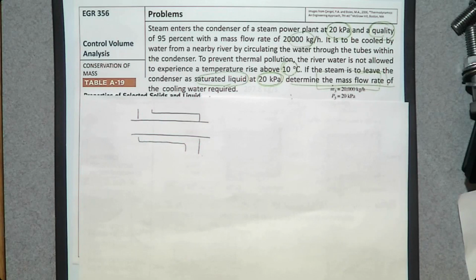If you open the engine room of your car, in front of your engine, what do you see? Radiator, right? They are an example of a heat exchanger. You see a number of fins, so that we can increase the surface area between the coolant and the air flowing, so we can increase the rate of heat transfer between coolant and air.